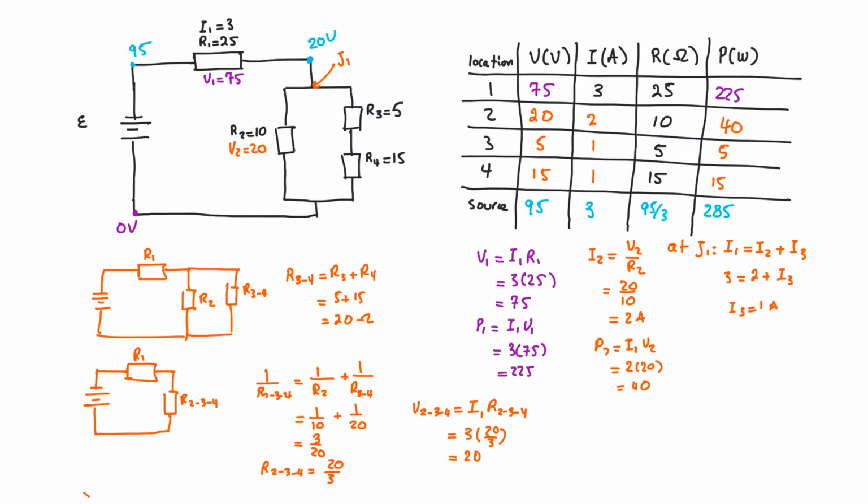In summary, whenever we have a circuit which has a lot of resistors, especially if it's a mixed circuit, then equivalent resistance is a fantastic way to find information about it. Usually in these questions where we have a lot of resistances and not enough current values, combining these will allow us to make a smaller circuit. And if we have even one piece of information about the current, then we can figure out potential differences across different regions of the circuit.